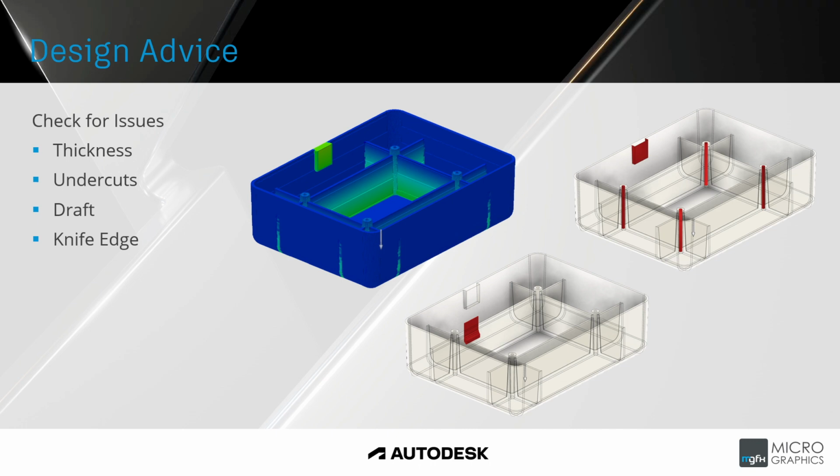Lastly, the tool can analyze for knife edges. Now, we don't have any images of knife edges, but this would basically highlight any sharp edges that could potentially break off in the mold when the part is demolded. In the case of this part, they would potentially be at the top of the ribs if those ribs came to a sharp point. That would then be highlighted as a knife edge.